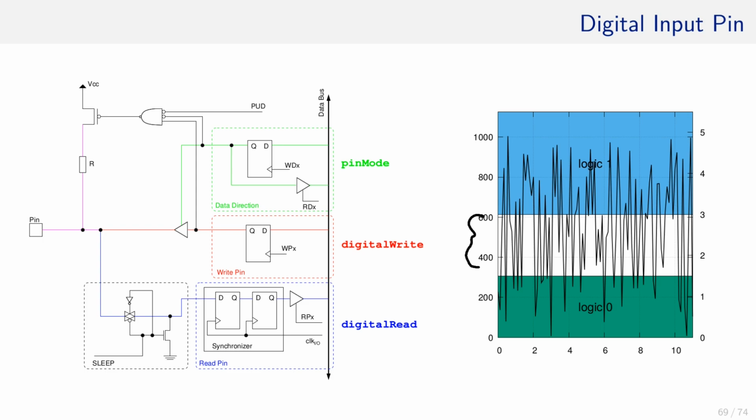Every update consumes power and introduces a bit of noise on the pin line. Imagine that the noise caused by the update is just enough to cause another update. That means especially this flip-flop here changes its state even faster than clock I/O.